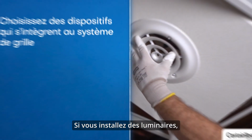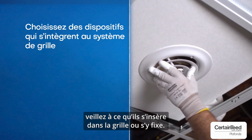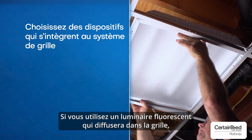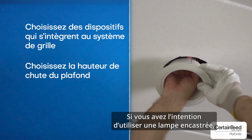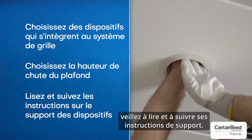If installing fixtures, choose one that will either fit into the grid system or can be attached to the grid system. If you're using a fluorescent fixture that will sit into the grid, you must consider how much the ceiling will need to drop to accommodate the fixture. If you're going to use a pot light, ensure that you read and follow the directions for supporting the fixture.